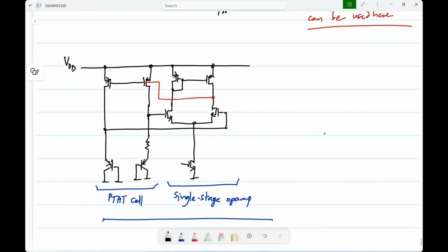Capacitor, where? So basically, it does have one gain stage, and the other one will not have a lot of gain. So you may or may not need a stabilizing capacitor, but if you do need one, you can, for instance, connect a large capacitor there, and then make that the dominant pole, and the circuit will be well behaved.